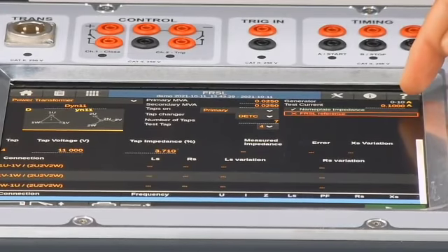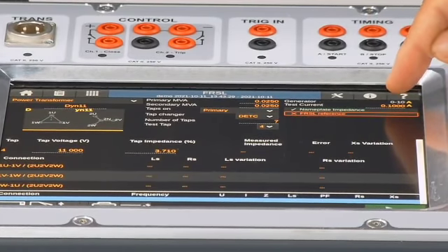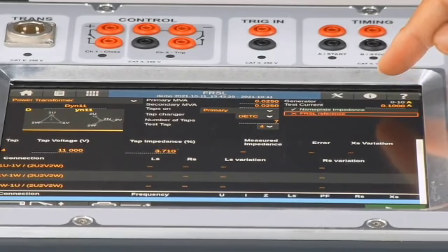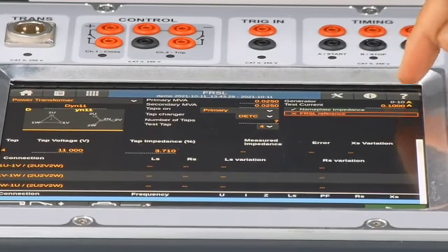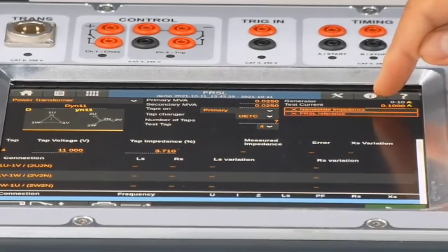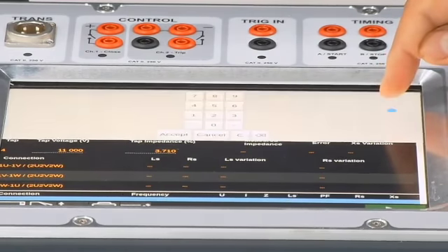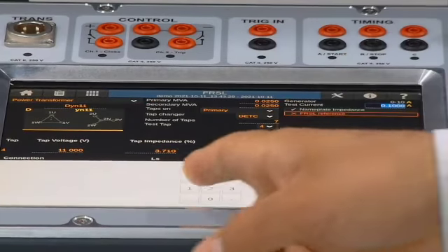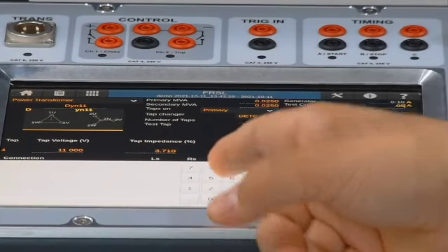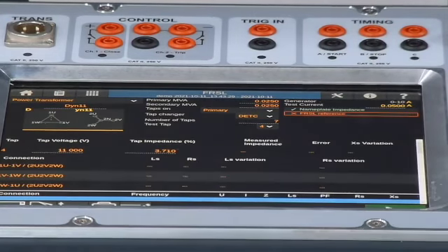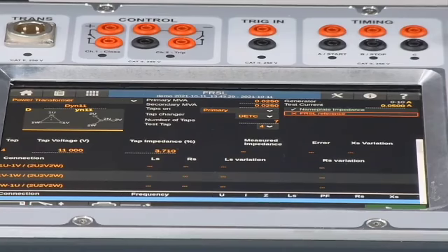I have here 0.1 amps. I said in the beginning that I will explain why I'm using very low current, because it does the job for me. I don't need to go for higher current. For this disk, I will again reduce it even more. I will put 0.05, which is 50 milliamps, even half the current I have used in the short circuit. I will explain why during the test itself.